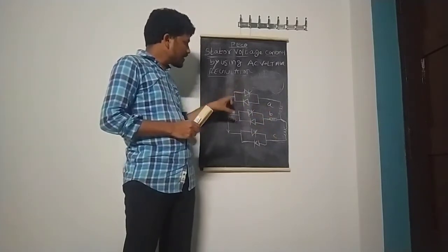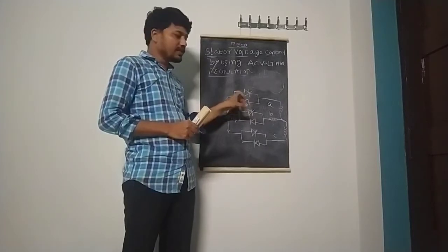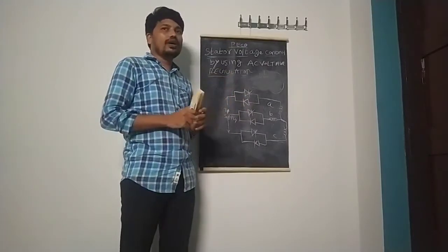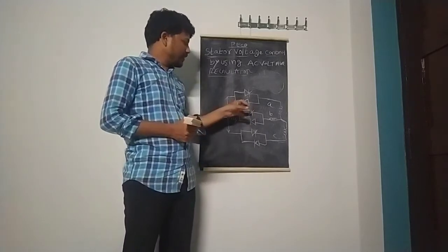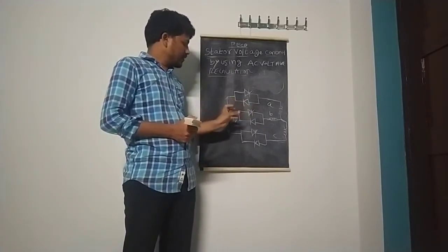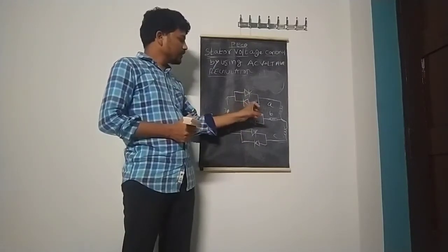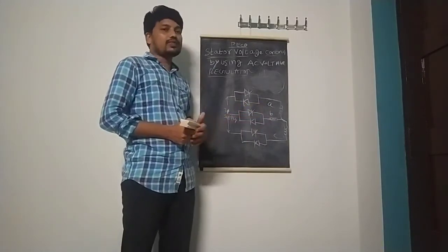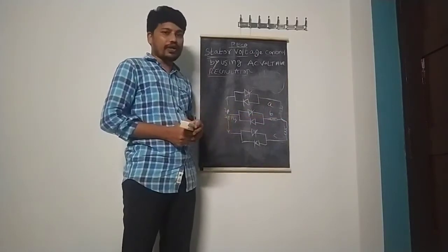With the help of this AC voltage regulator, especially the three-phase voltage regulator, which may be half wave or full wave. We are using the three-phase half wave here. Three-phase supply is given to the three-phase half-wave AC voltage regulator. Through this, the supply goes to the corresponding stator winding of the three-phase induction motor. Then we can control the speed of the motor here.